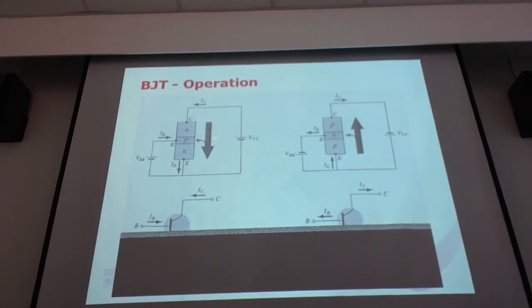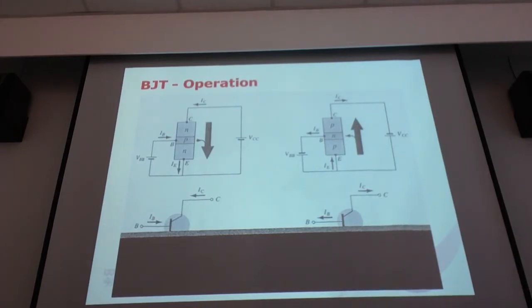This is a kind of switch here, the BJT. In other cases, we have to close and open the switch only. But in this case, by applying a certain voltage, we can control the open and close status of this circuit. Can we just apply VBB or just apply VCC? If we just apply this base voltage, there will be no current at all. So even if the switch is closed, what is the significance if there's no current flowing through?